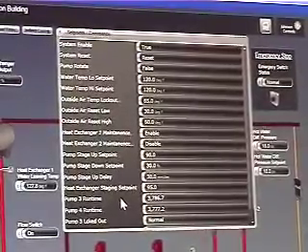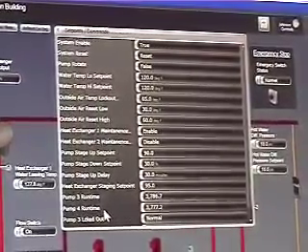The way this works, and we kind of mentioned it before, is that every time the system goes to turn on, it's automatically going to rotate whatever pump has the lowest run time to run that. If the system went hot water, we're probably going to run all the time. If we don't rotate them, the one will always run, the other one won't get any run time. So that's why we do try and rotate them.